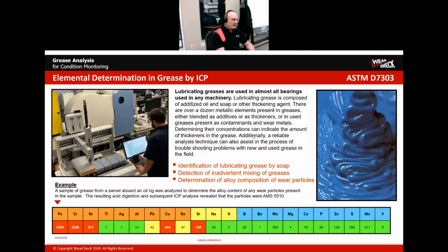One nice thing about this is that in oil, there's a homeostasis in terms of the wear particles and the wear debris that's present in an oil sample. As the oil is circulating through the system, particles are being generated through abnormal wear conditions or just through the normal oxidation processes that are occurring on the metal surfaces themselves.